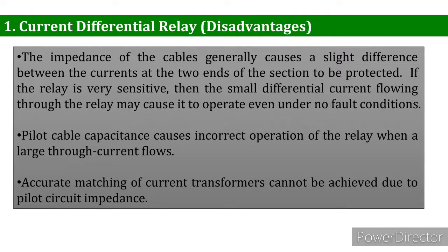Thirdly, the accurate matching of the CTs cannot be achieved due to pilot circuit impedance. As we all know, while manufacturing there is always a difference between two CTs, and two CTs connect through different wire impedance. So we cannot match, for example, 100% two different CTs.